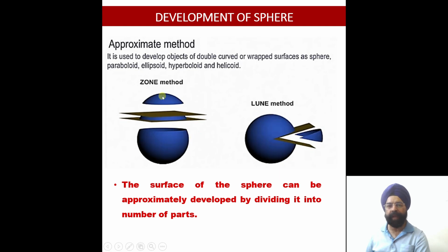We are going to develop the top hemisphere of this sphere, that is 50% of the sphere, and the development for the remaining 50% will also be the same. The topmost portion contains this spherical portion, so as an approximation, we will assume that this is the axis and we are going to join this over here, and it will approximately behave like a cone.